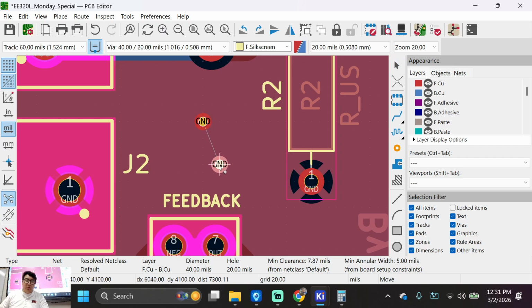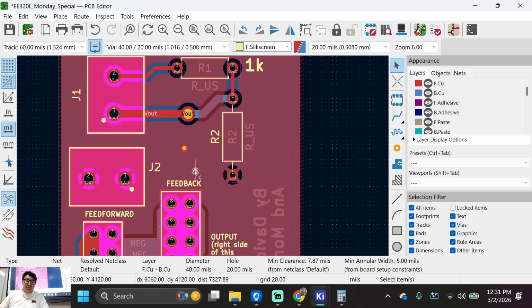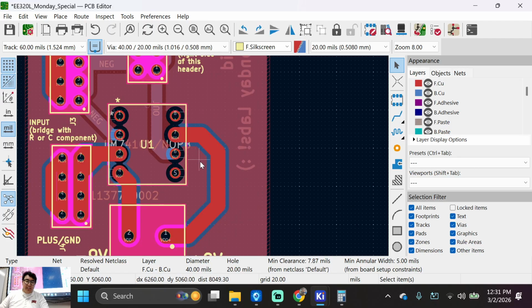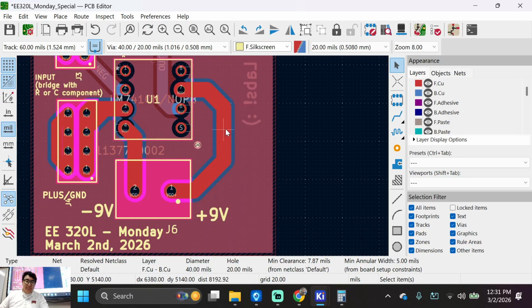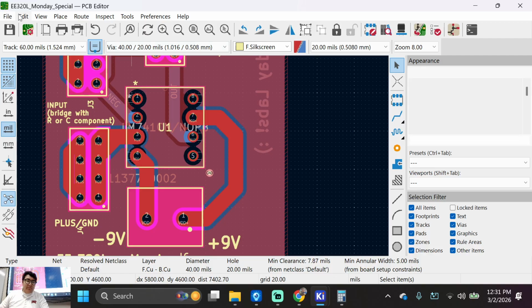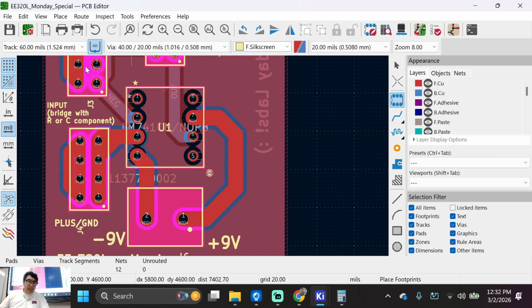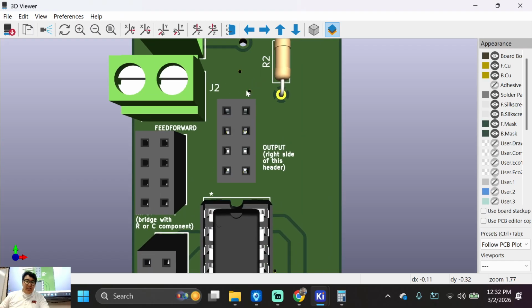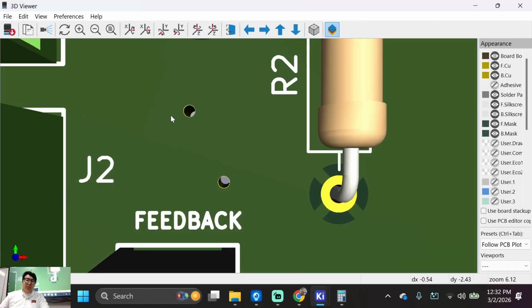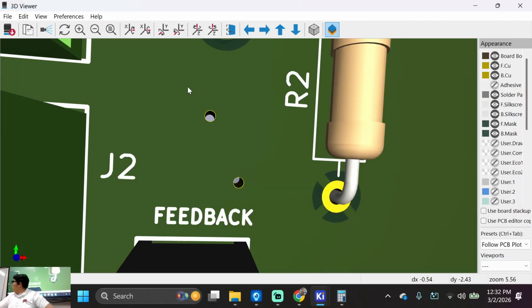Okay, Control C, Control V, Control C. I'm going to put one right here. Control V. I'm going to save, Control S, View. Oh, come on, Escape, View, 3D Editor. See that right there? Those are ground vias. If you have an Arduino, you're going to see these tiny little holes, okay? I don't have one on me, but these are called ground vias, okay? They connect the top and the bottom coppers, all right?